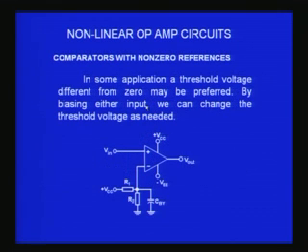Now, you also saw in the demonstration that we need not have zero crossing, but we can also have some reference voltage. We have used a potential divider R1 and R2, and the midpoint was connected, the same circuit we showed in the demonstration. This is again a method by which I can convert a zero crossing detector into a comparator for comparing a threshold voltage, which can be chosen by properly choosing the R1 and R2 values.